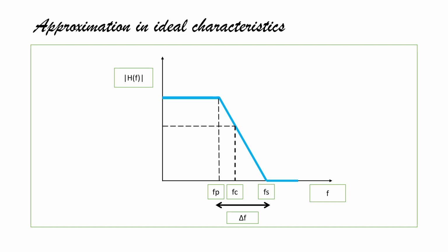It is from the pass band to stop band. At the starting point, it is the maximum value, that is 0 dB, and this is the 3 dB where the cutoff frequency is. So here it is represented in dB scale. If I represent it in the absolute scale, we start with 1, and rather than 3 dB, this will be the value 1 by root 2, that is nothing but 0.707.